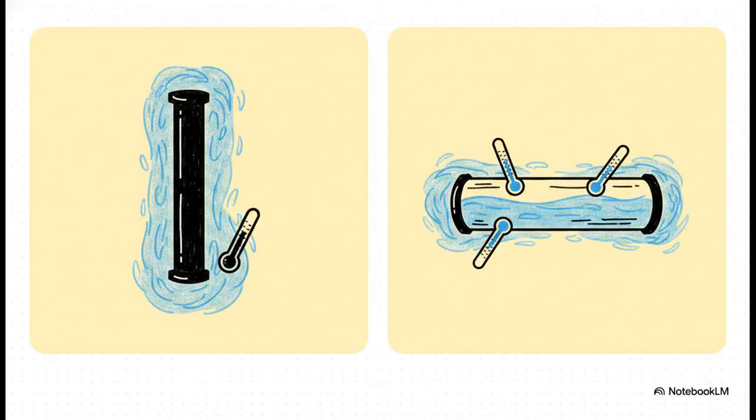Now, TEMA creates this brilliant sort of fork in the road for determining design temperature under RCB 1.42. It all boils down to where a part is physically located inside the unit. For parts that are not in contact with both fluids, that's governed by 1.421, the purchaser specifies the design temperatures separately for the shell and tube sides, and then the code just provides the allowable stress limits. Simple enough, right? But for parts trapped between both fluids, like the tubes themselves under 1.422, the design metal temperature has to be based on the operating temperatures of both the shell side and tube side fluids.